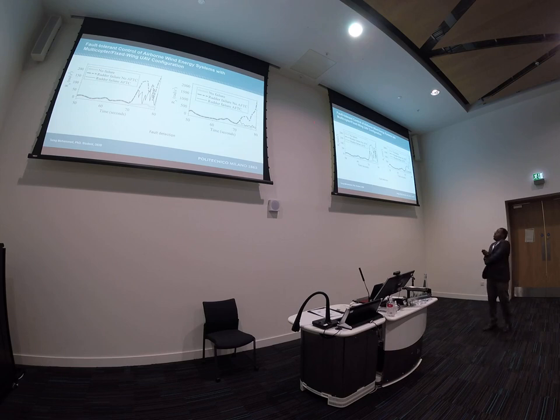Here we have the residual from the tethered axis. At the second 17, the residual starts to increase. And in the black line, when we engage the active fault-tolerant control, it decreases again. That's why it's important to use a threshold lock. Also, we found that Rz is also able to capture the failure. You see here, the residual starts to increase, and when we engage the active fault-tolerant control in the black line, it decreases again. But in this dashed line, we are not applying any fault-tolerant control, and the residual starts to increase.